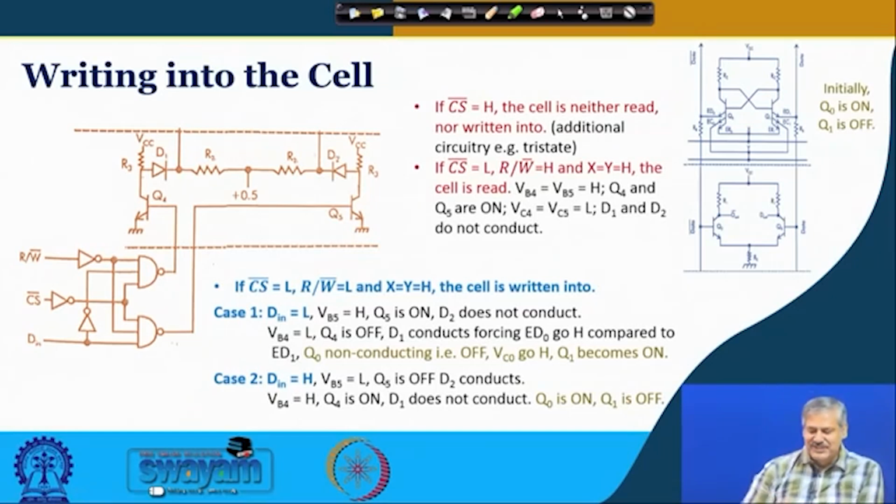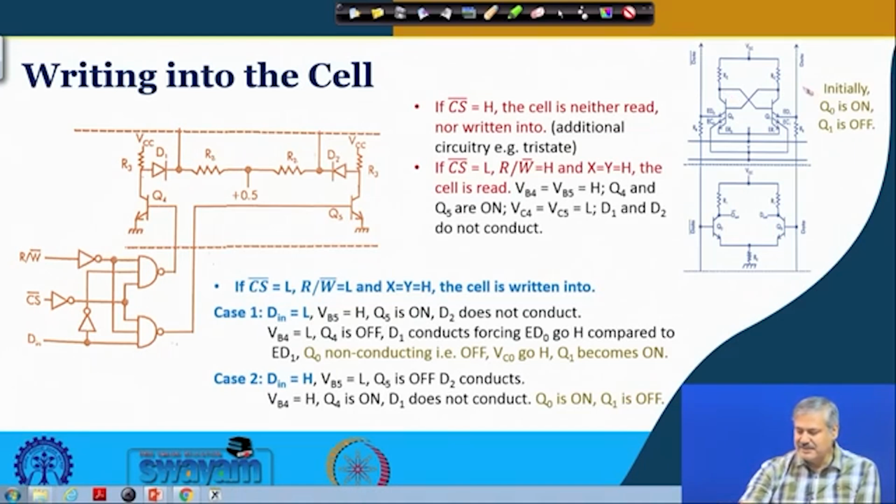Okay. So, the circuit that you can see now, this is the basic memory cell, and generally we consider Q naught is on and Q1 is off, right, and this is the data line or the bit line, and this is the reading or sense amplifier. So, this is D out bar and this is D out, which we have already seen.